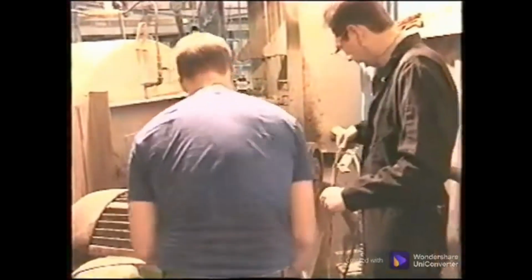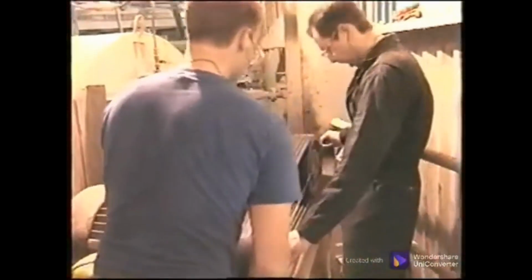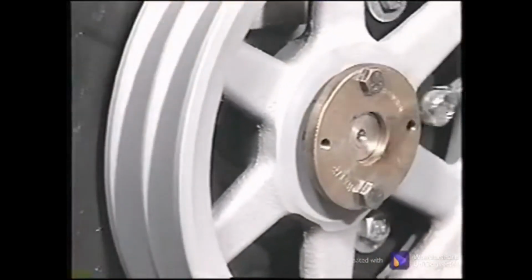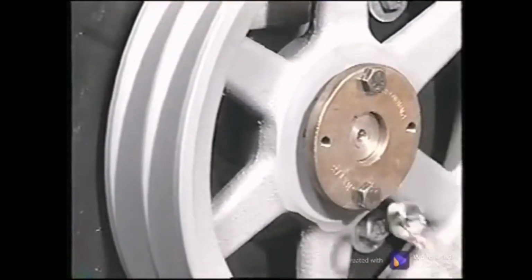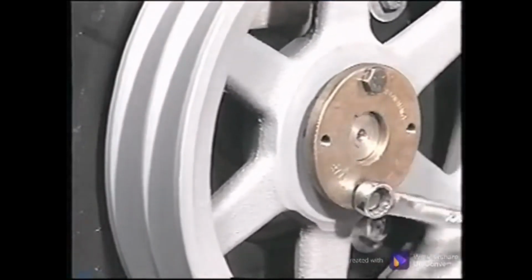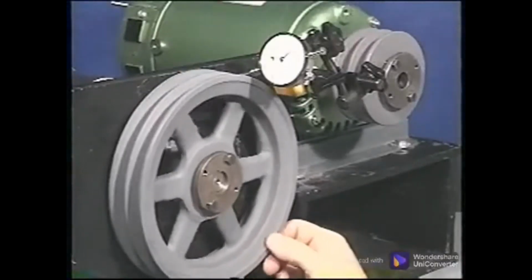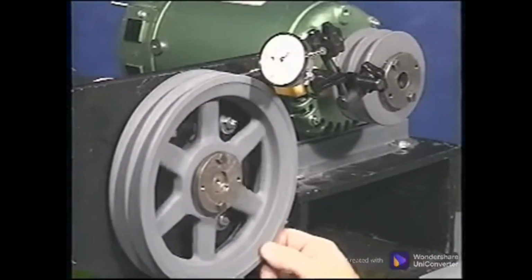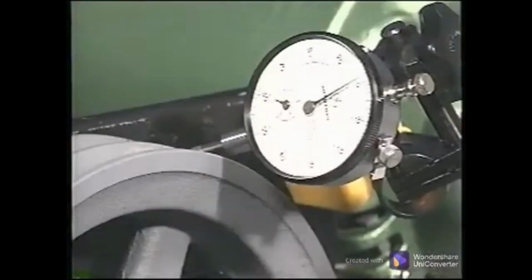Position the sheave on the shaft and rough align it using the string or straight edge. A taper bore sheave and bushing require extra care to be square to the shaft. The bolts should be just snugged up and the runout checked with a dial indicator to ensure that the sheave is square to the shaft. Place the dial indicator on the side wall of a groove and not on the face of the sheave.